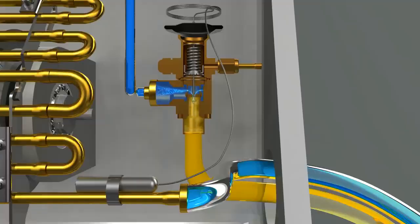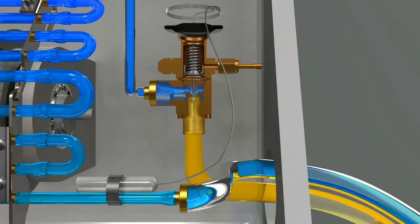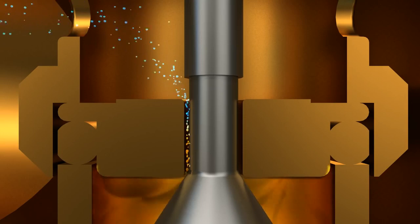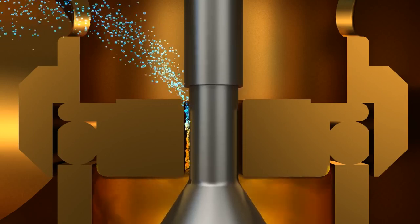The expansion valve is connected to a sensible heat storage that detects heat. The sensible heat storage is installed at the exit of an evaporator and detects temperature. Inside the storage is fluid sensitive to temperature changes, and as the temperature at the exit of an evaporator rises, the gas pressure rises, which in turn presses on a spring to send more refrigerant to the evaporator.